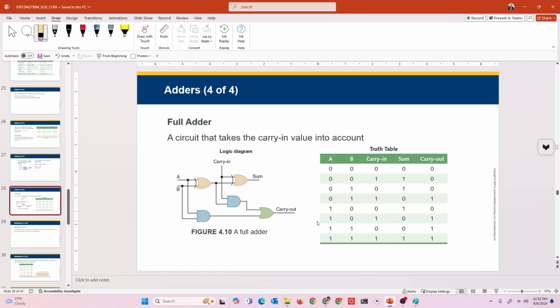So this is a full adder. So it's actually considering the carry, the carry in from a previous calculation. And then you're using it to provide a sum and another carry out. Here's the carry out. You don't need to understand the whole thing, but feel free if you want to. Generally, if you do the addition, you'll see. But this is an AND, this is an AND, this is a plus, and this is a XOR. Okay.